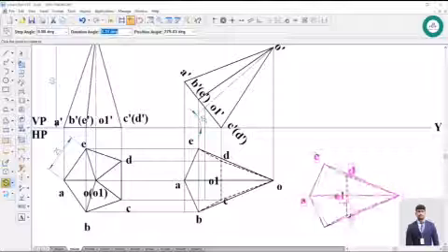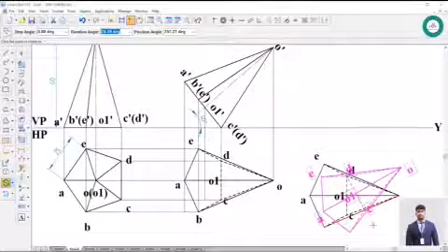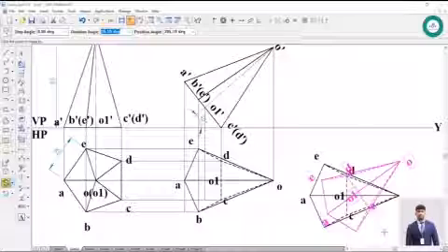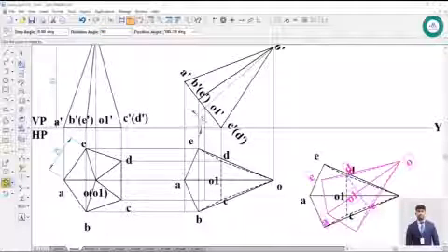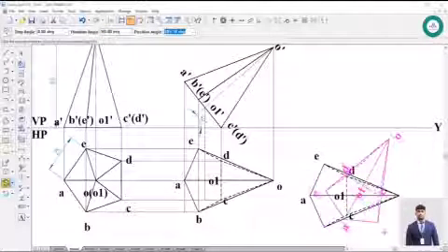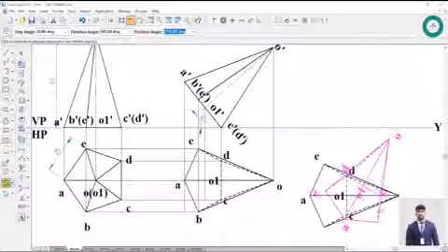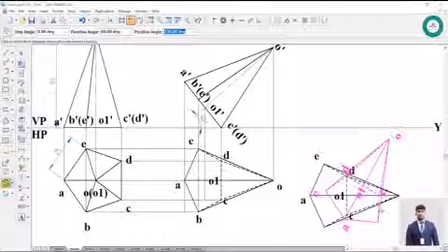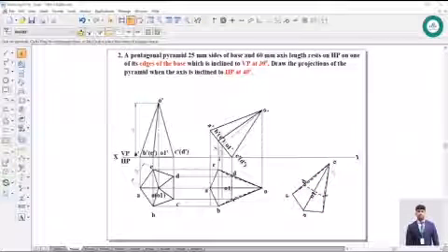I mean to say I have selected the vertical line C and D. First I have clicked the point D and next the point C. So the angle is given 30 degrees. So 90 minus 30. You can place this way as well as this way. So I'm placing this particular way. After placing this, ensure the apex should not touch the XY line.